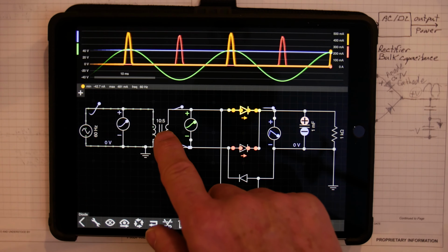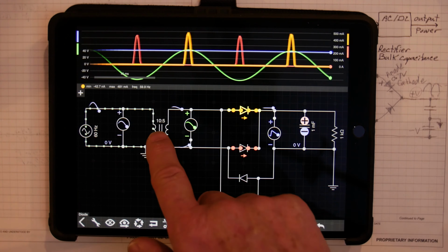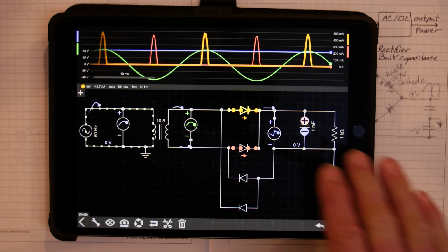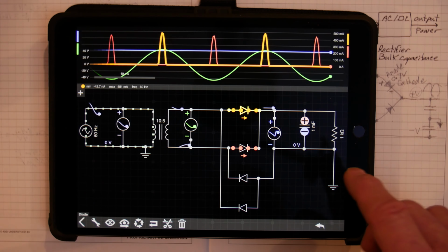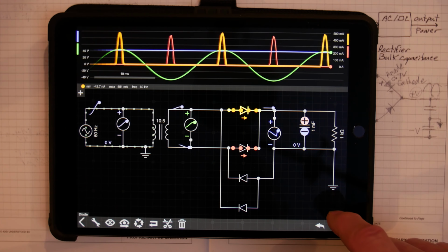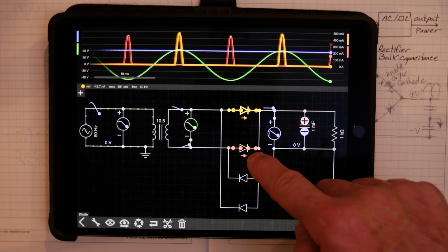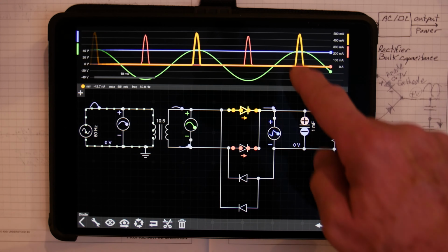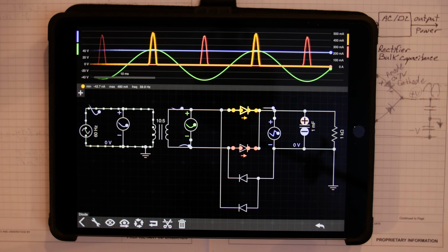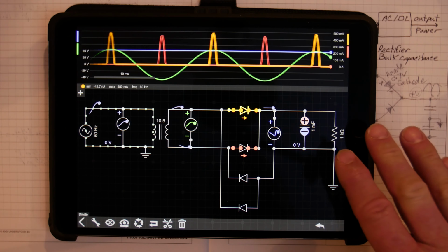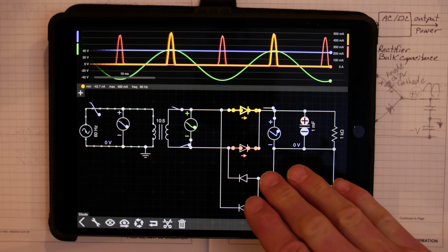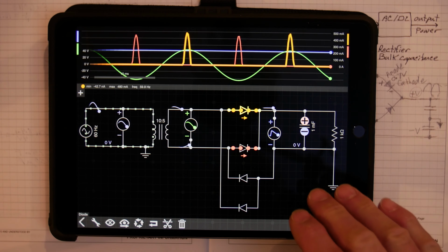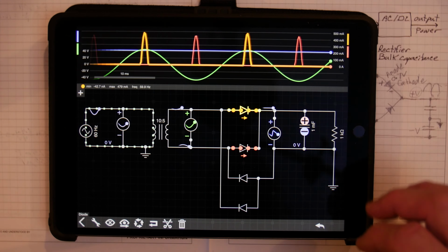And you can also see that with the higher currents we were getting some voltage drop across our transformer. So when we select these parts, we have to be cognizant of all those things. And I have a different current rating on each diode, so one diode's dropping a little bit more voltage than the other one. So you can see how the diodes, the capacitor, the transformer, all these things play a role in what you end up with voltage here.